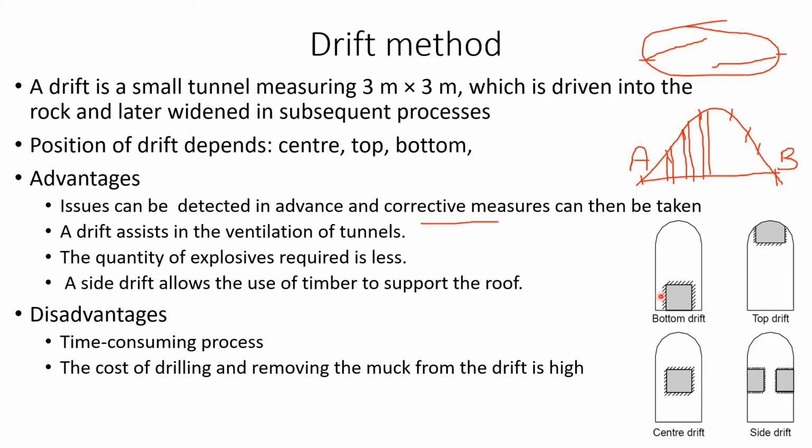The quantity of explosives required is also less, because we start with a small drift and then later it's expanded. And as I told you, when side drifts are provided, this can be used to support the roof.